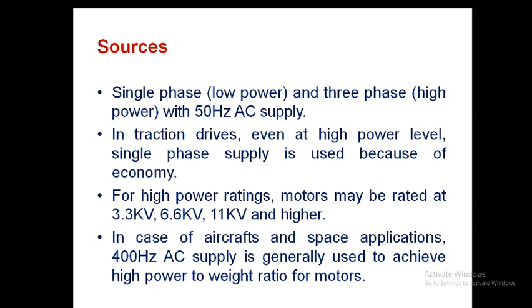In case of aircraft and space applications, weight is a criterion. We need to reduce the weight in aircraft or space applications. To achieve that objective, the same AC supply with high frequency is used. When you go for higher frequencies, the inertia will be reduced and the magnetic component size will be reduced.